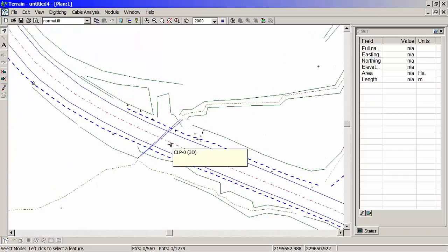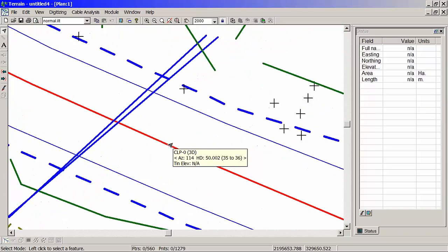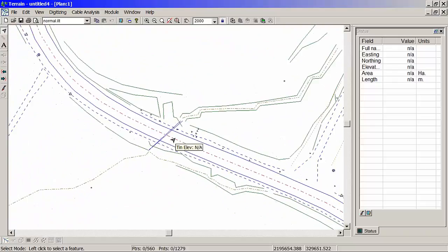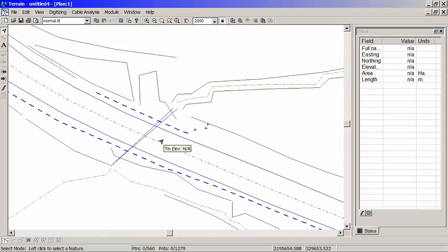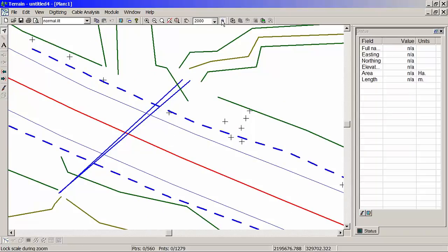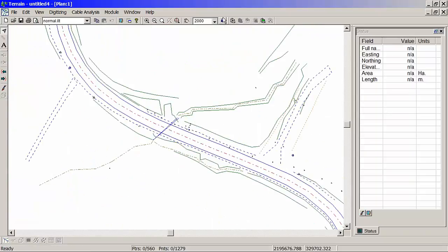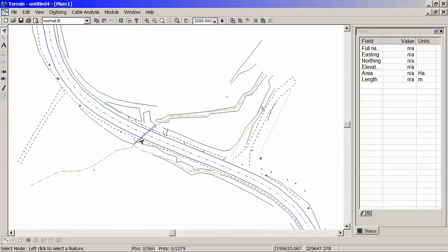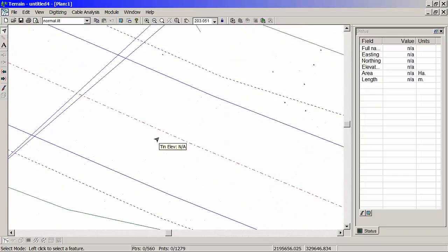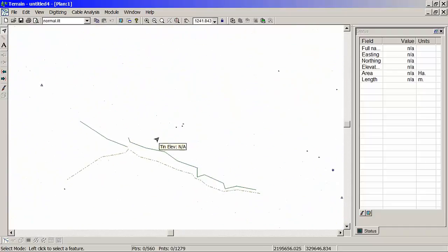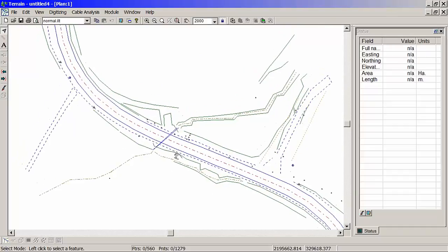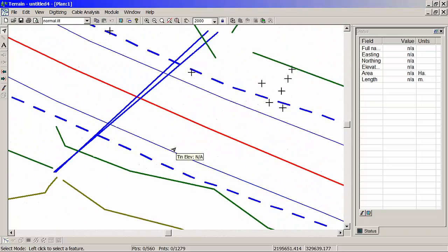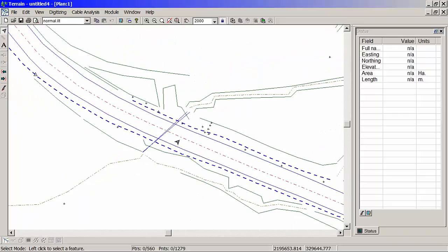If you roll in on the center wheel button, you can see my line work is getting thicker. As I roll out, it gets thin. That's because my scale is locked. If I unlock my scale, press the lock scale button until it becomes the same color as the rest of the background up here. You can see that my scale changes, my line work stays the same size. If I lock my scale again and set my lock scale, my line work becomes thicker. So it's basically zooming.